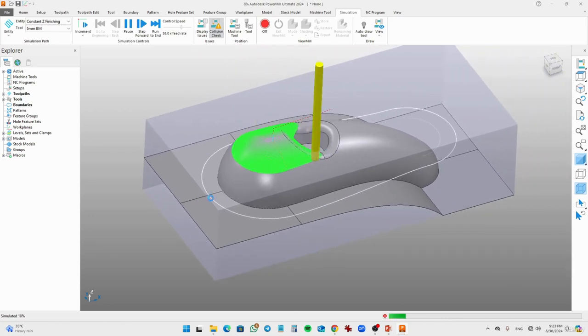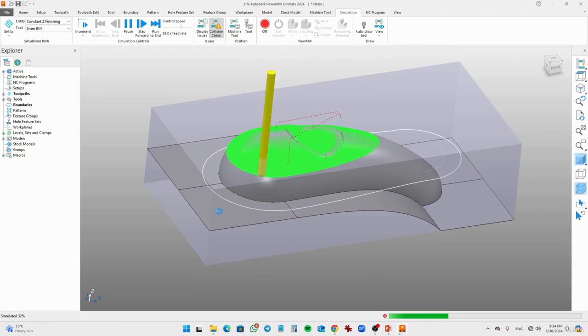And we have the boundary set up. So within that boundary, the cutting tool performs all operations, okay? It will never go outside of that boundary. So this type of toolpath gives you a very fine finish on the surface. It is mostly used after the rest machining operation. The smaller the step down, the more surface finish it gives you.